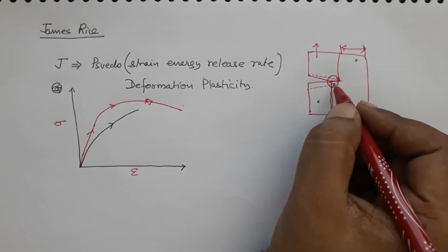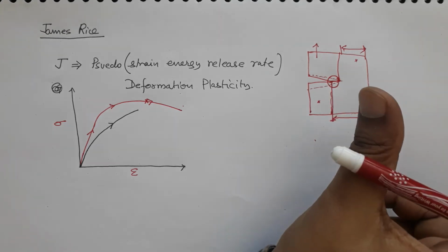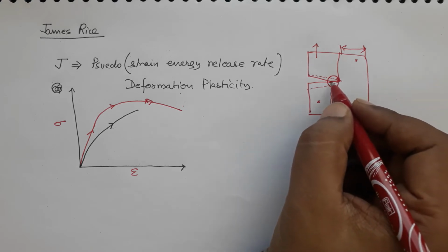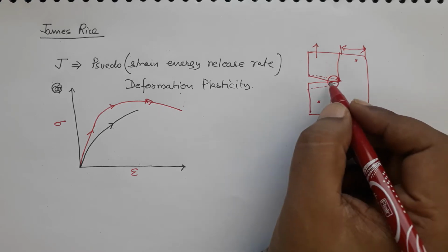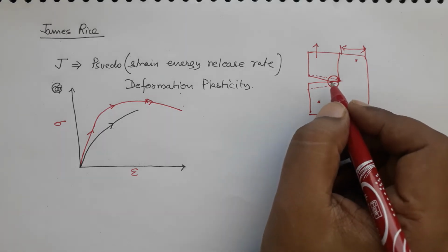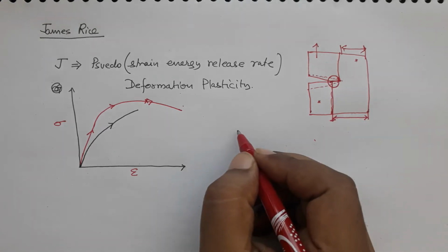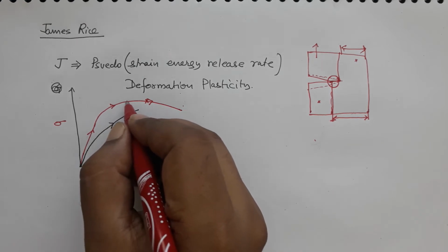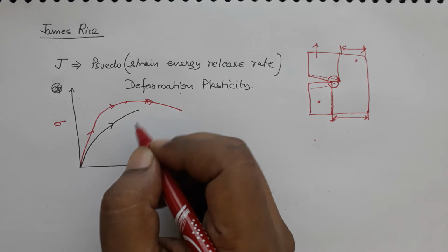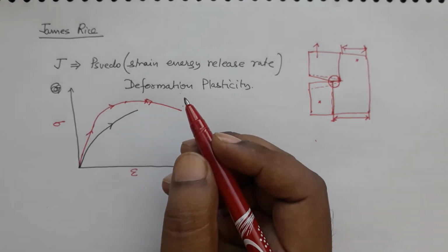That amount of material, because the crack has opened up that surface, what has happened is that part has unloaded. That part is now stress free, there is no load on that, right. That is a kind of unloading because that part was actually loaded at a higher stress and then you unloaded it, right. And we know that at crack tip stresses are much higher than yield strength.